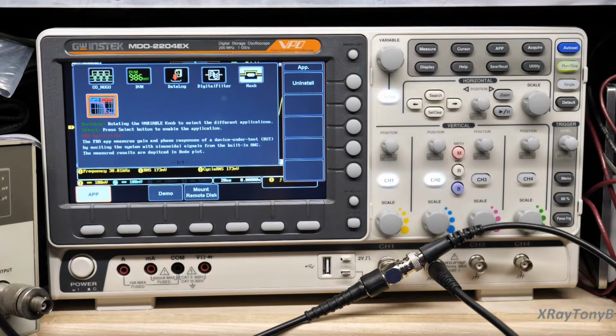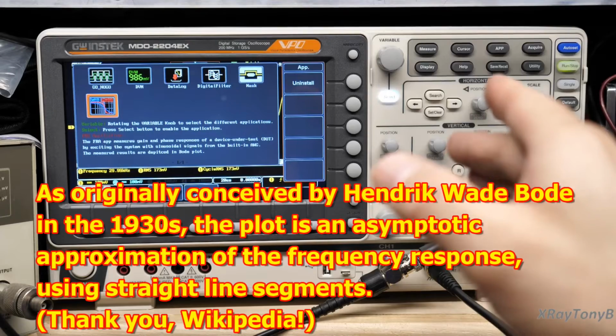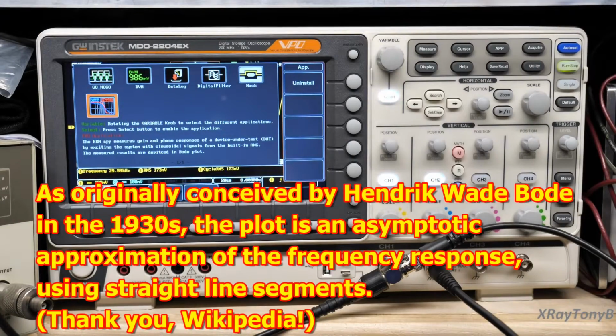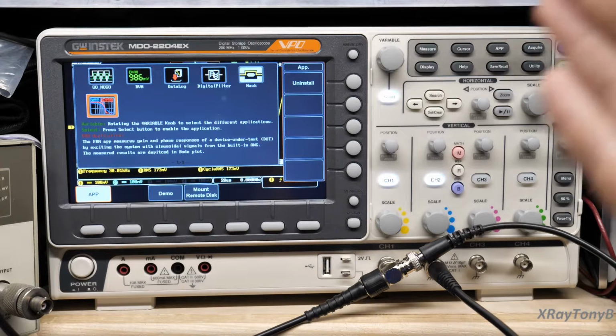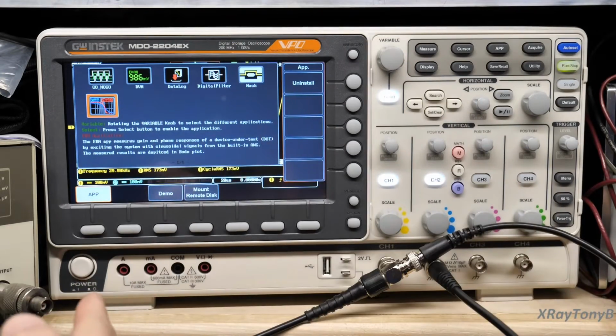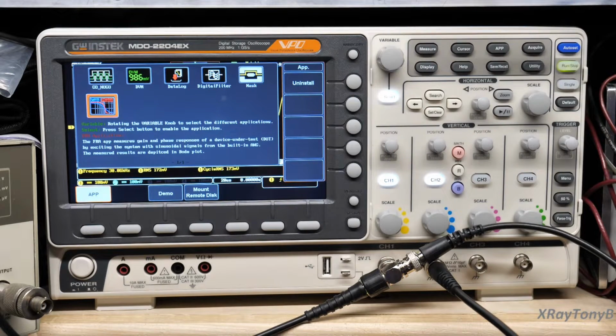What is a Bode plot, you might say? Well, it's a graph that represents the gain of a signal through an amplifier, through a device under test, versus the frequency being applied to that device under test. And it also shows any phase shift that may happen between the input and the output. So what good is that going to do us for a stereo amplifier, you might say? Well, it's going to show if the amplifier has a flat response curve.